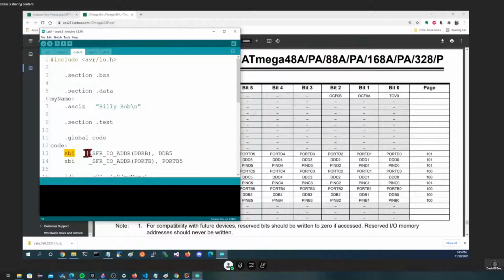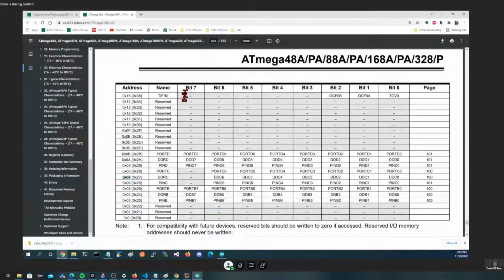And we can look that up in the data sheet to see. Basically, a set bit I/O or clear bit I/O would be the name. The I stands for input output. Now, if we look at these, we're worried about port B. But along with port B or any of the ports, we get 2 other registers.